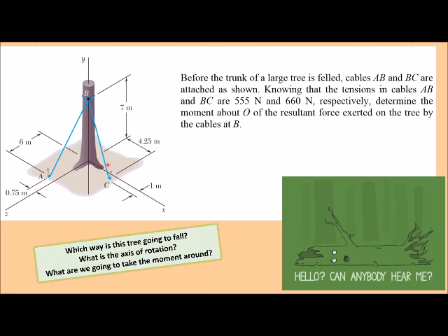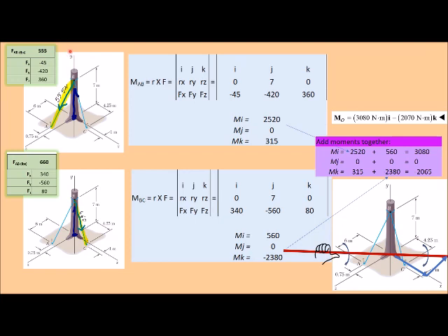So moment really is a stability. A lot of failures happen by something rotating around a point. This is describing anything that's falling over. It's a moment and it's a rotational fight that you're doing to keep things stable. Each force creates its own moment.